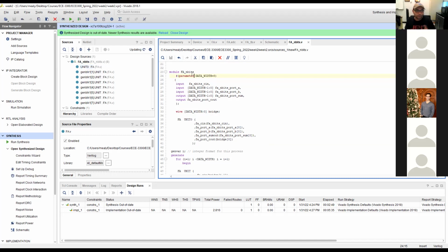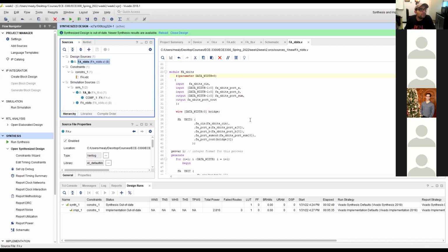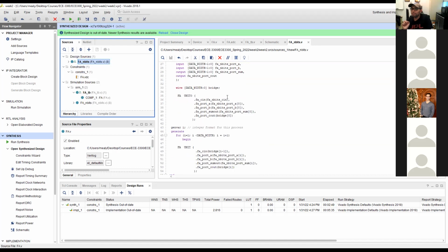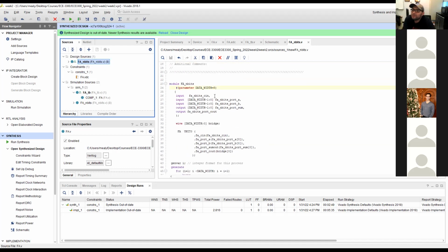Okay. Now, let's make a test bench that will benefit from what we are doing. So in the test bench, we're going to instantiate this block. Do you guys agree? Since I have a parameter, I can instantiate anything else I want. Why do I need to run 8-bit? I can make it 4-bit, and if it works, it works. Then I have to change a little parameter inside, then I'm done.